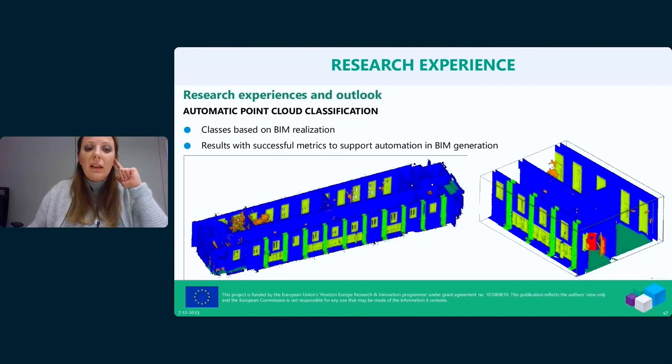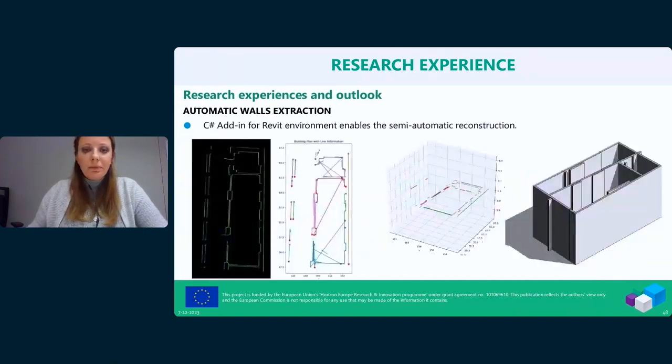So basically we can semantically enrich our 3D data and divide the data into clusters of points belonging to a particular class. And this is quite important for the possibility to work in a BIM environment with fewer data, so single classes like walls or windows or pillars and so on, and have a more manageable environment.